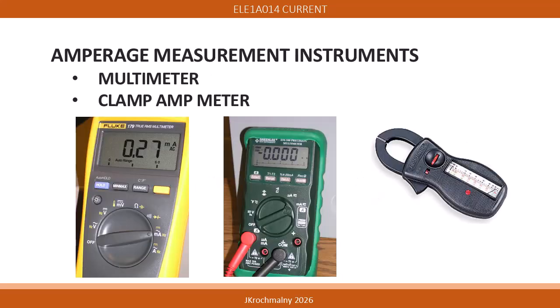The multimeter is used for low amperage measurements. Amperages of values in milliamps will typically be used. For higher amperage applications, such as measuring electrical motor amperages, it would be dangerous to break into the live and exposed electrical circuit. For this reason, clamp-on amp meters are used.